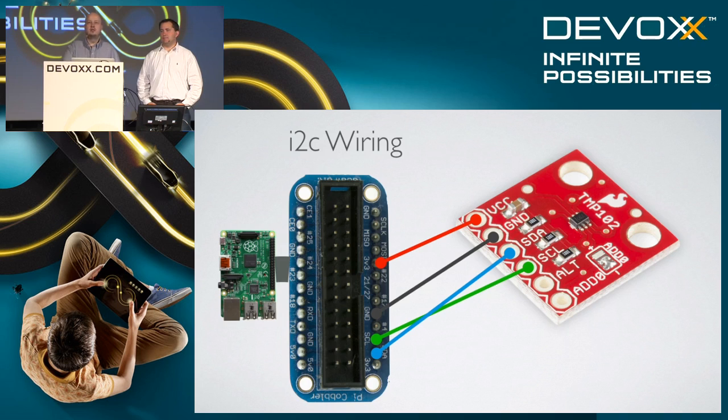There's 4 wires, so you have your positive voltage, your ground, and then 2 data wires, data and a clock. And you can connect as many devices as you like up in parallel, just one after another, and chain them up. I think we've had at least up to 10, 12. In theory, you can get up to 250, but I think you might have issues before you get there. But generally, you can connect a pile of these devices up. Each one has a unique address and is individually addressable, and the programming of them is pretty simple, as we'll go into.